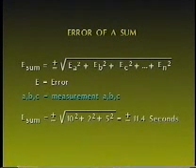This answer demonstrates that the total error in a group of measurements having varying errors is only as strong as its weakest link, or angle in this case. Measuring the other two angles more precisely than the weakest angle does not improve the overall precision of the sum of the errors. You now have the tools necessary to begin determining the error in most of your survey measurements. Take time now and try to solve the point location problem in your workbook.